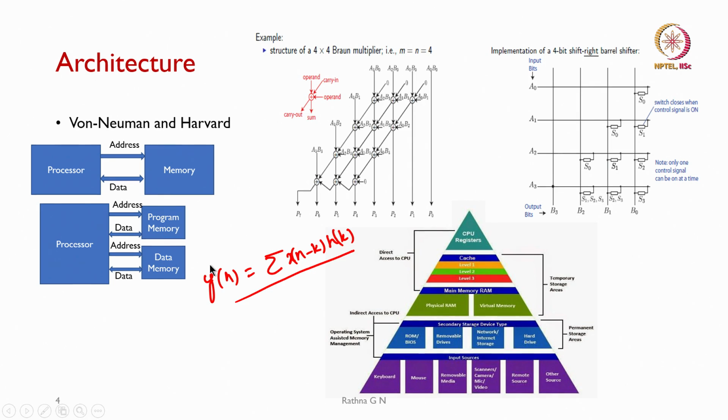And then for multiplication, we said we will go with the Braun multiplier, which is much faster. These are the 2 inputs for the 4-bit Braun multiplier we drew. In this case we are going to have an AND gate before the data comes into our Braun multiplier. As you can see, the longest path delay is from this path to the final output.